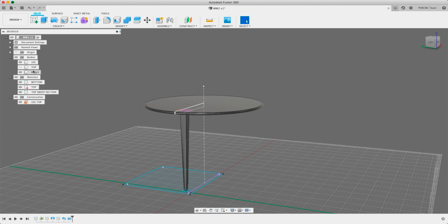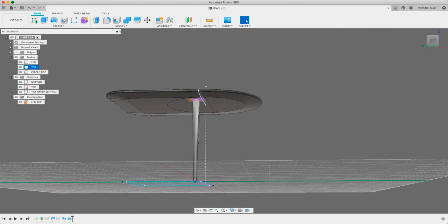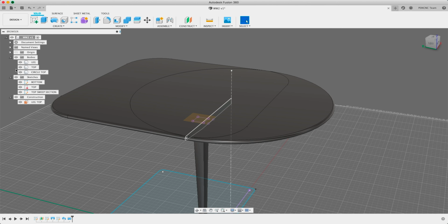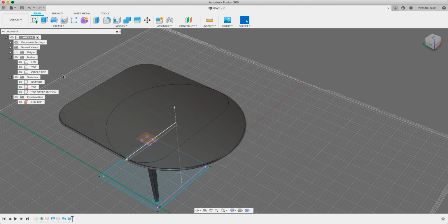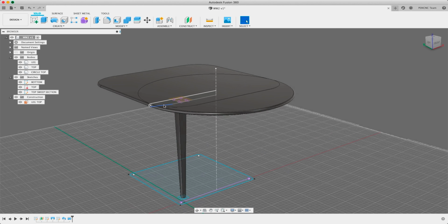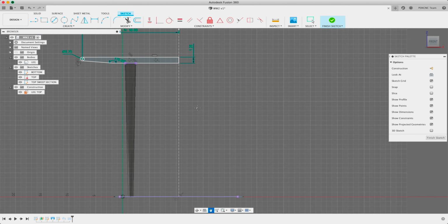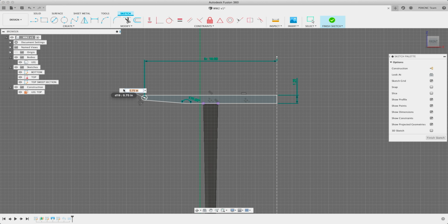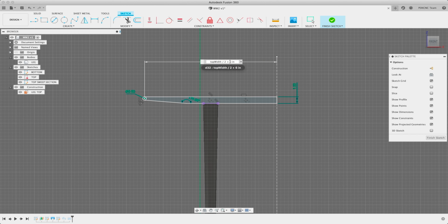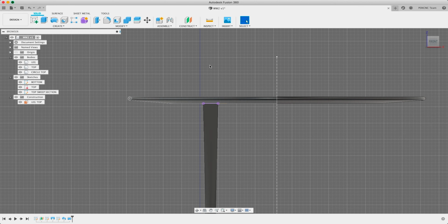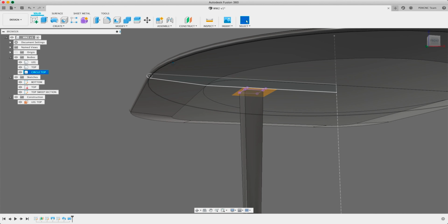So now we've got a second version. So we'll say circle top of our design. What's cool about this is anytime we want to change any of this stuff, we can just go into our sketch of the top sweep section, change any of these things, smaller profile, thinner table, maybe we want it slightly longer. We finish our sketch, all of that's been updated perfectly.